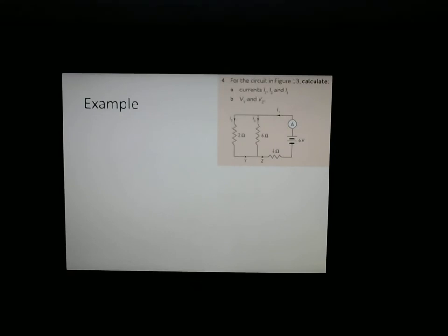Note, if something asks you to work out, say, the current, but doesn't actually tell you to work out the resistances, you don't have to. There are tricky mathematical ways around it using Kirchhoff's laws. So you could use that if you wish to, because we could write a couple of simultaneous equations using voltage loops.